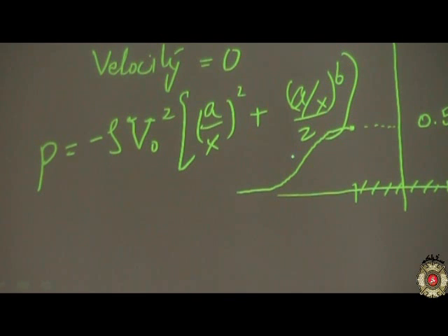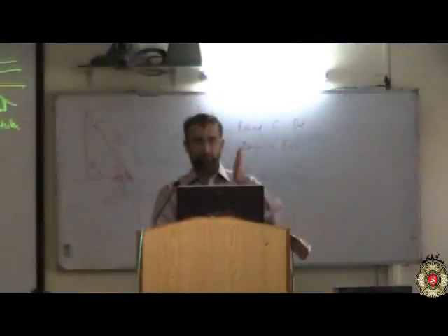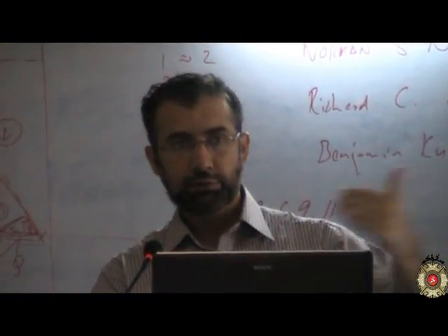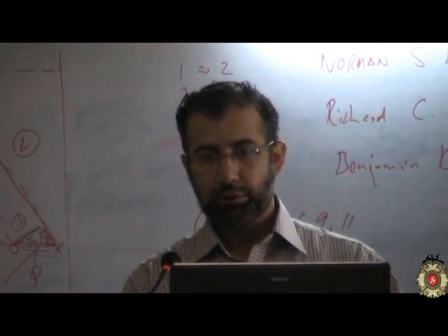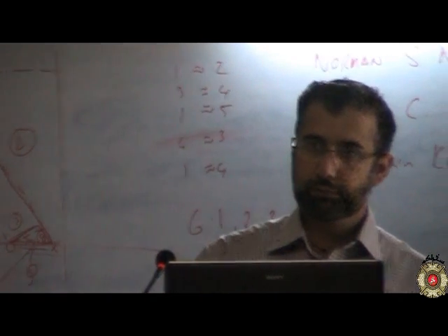F(x) is minus a, then things go down, but like kinetic energy, and then you have potential energy. Right, conservation. But the point I was emphasizing was there are different types of pressures. Static pressure, dynamic pressure, we'll talk about next time. In aircrafts, they have, let's say, just a hole somewhere here on the surface perpendicular to the flow that measures the static pressure, and for this one they have a pitot tube to measure dynamic pressures.